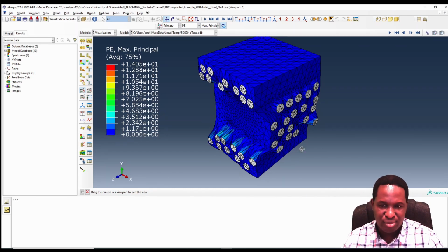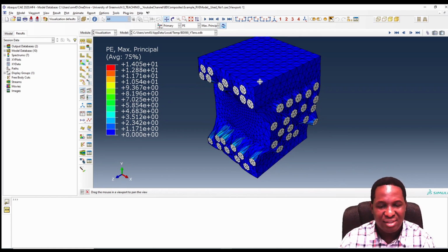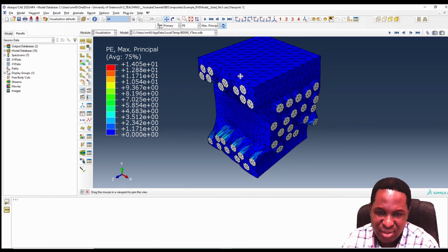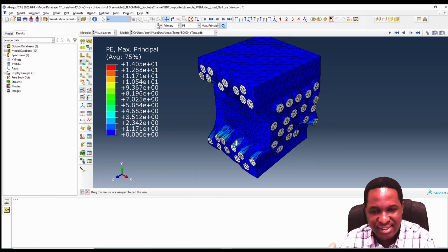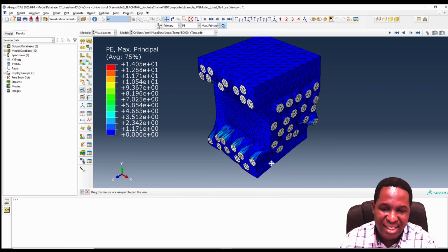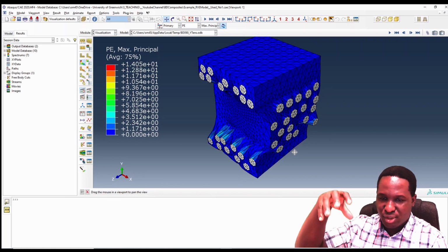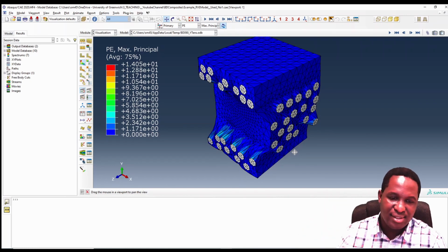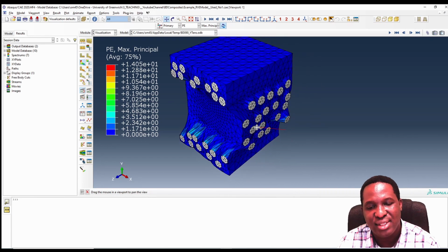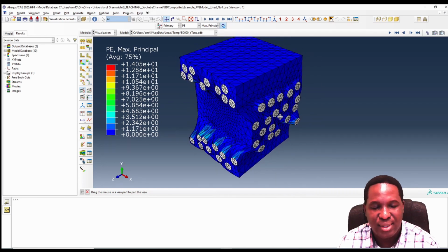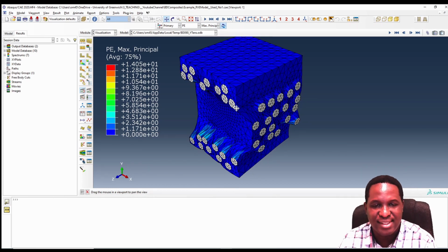As you're moving up, you're pushing in the Y direction, those fibers actually do not offer much restraint, much resistance, except the fact that, during the Poisson effect, they may resist movement. So there's an enhancement of properties, but mainly, this is a problem with laminated composites. On the outward plane in the y-axis, or in this case, what we call the z-axis, the fibers do not actually add much constraint, much contribution. Okay, it does provide some reinforcement, but not significant. So this is what we see with this.